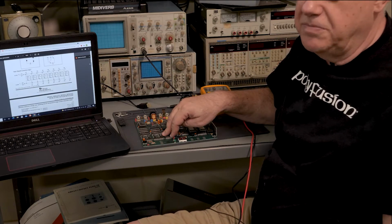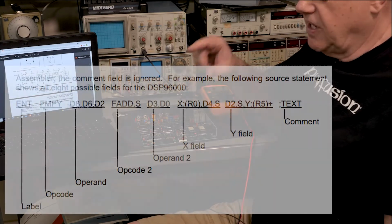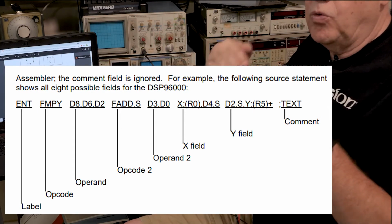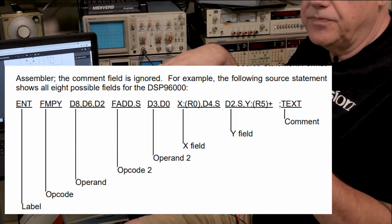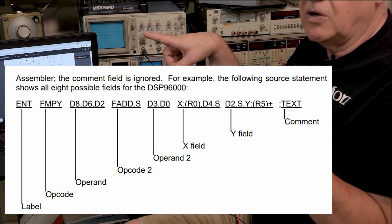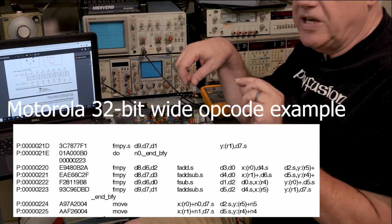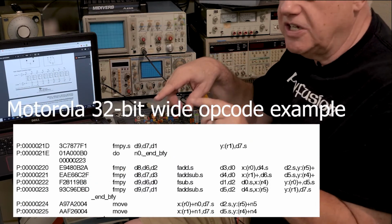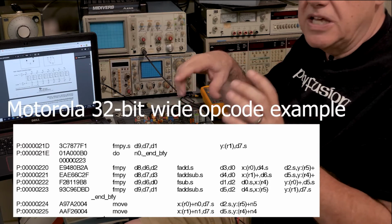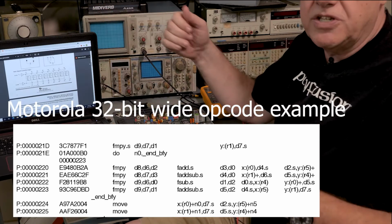opcodes don't have to be just what's coming out to decode the instruction. You can have multiple pieces of data within an opcode. So what do you mean by an opcode? That's what we call one instruction line of our program. And it turns out that it's very common in DSPs to have very wide opcodes. I've seen some that are 56 bits wide because the whole point is how fast can you execute one instruction. But if one instruction has multiple bits of data in it, then you can execute that one instruction and maybe have 4 or 5 things all happen at once in the hardware.